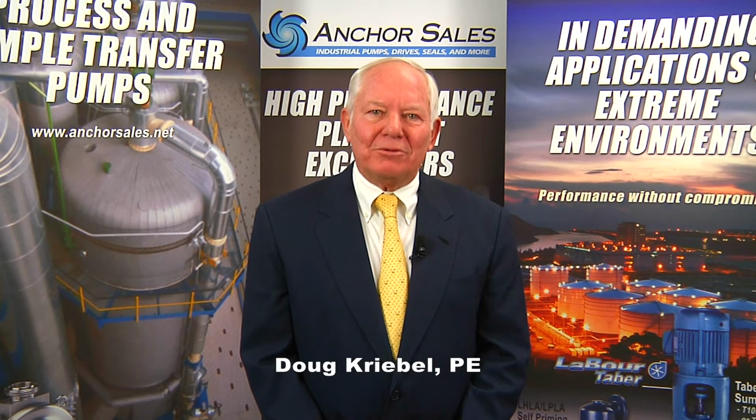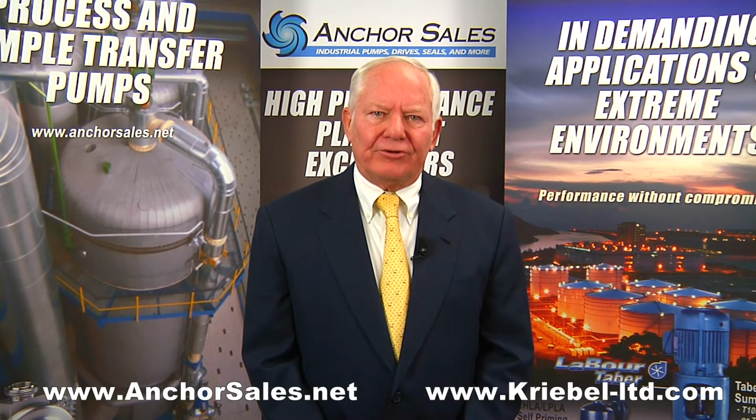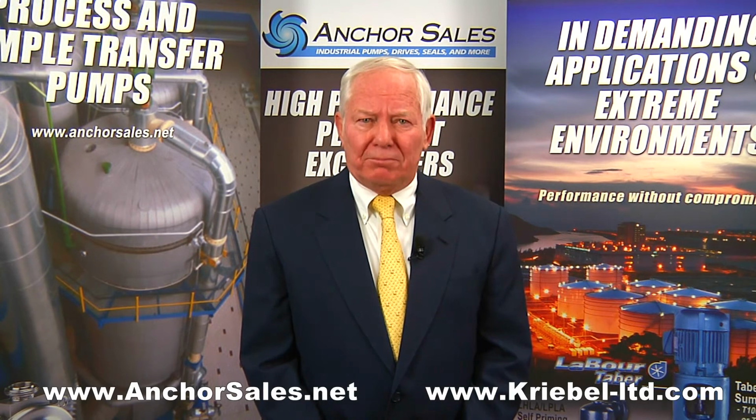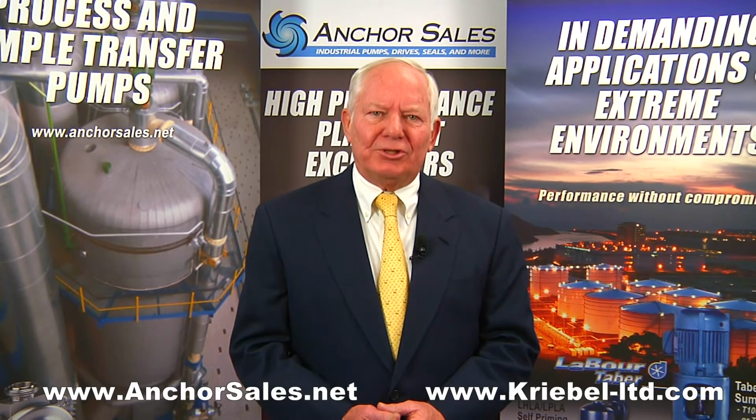Hi, I'm Doug Kriebel. If you're involved in pumps, sooner or later you will have to step a curve. This is the term given to determining new conditions for a pump when you have changed either the impeller diameter or the speed of the pump. There are several reasons to do this.